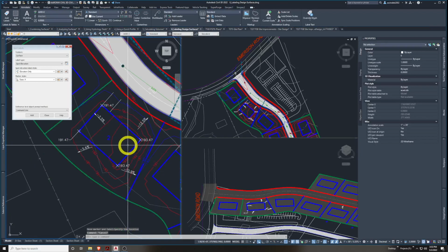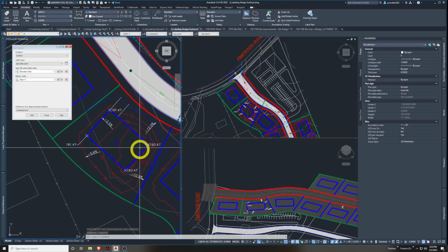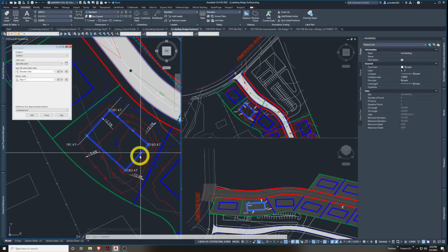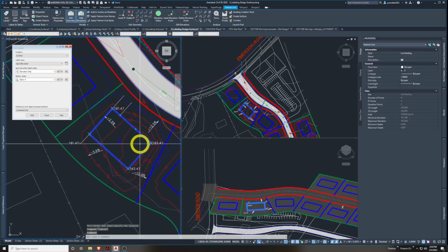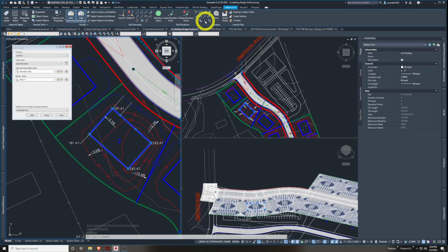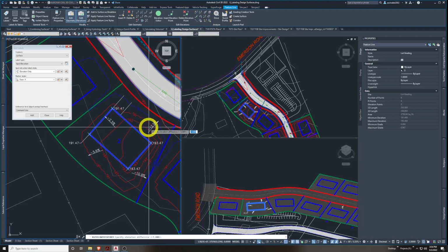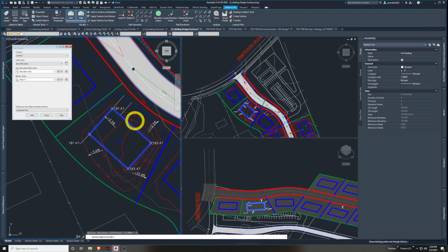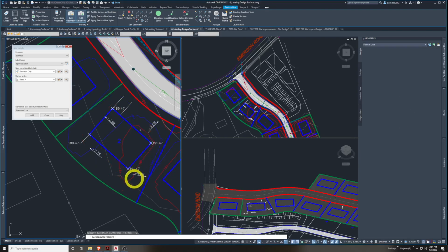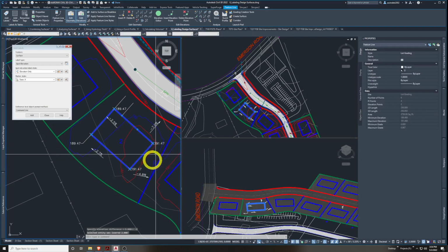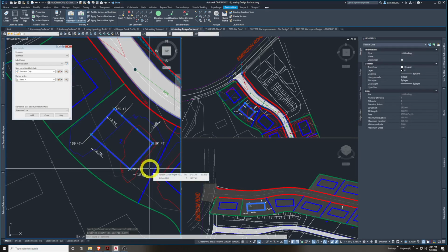So we've basically added them to each corner, but as with all Civil 3D labels, they're dynamic. So I'm going to pick my feature line here of this building pad, and I'm going to say raise lower in the edit elevations here. And then I'm going to specify the elevation difference of, what do we want? Let's go -2, so down 2 feet. That will update the surface and everything with it, as well as the contour labels. They all went down 2 feet as well, as you see.